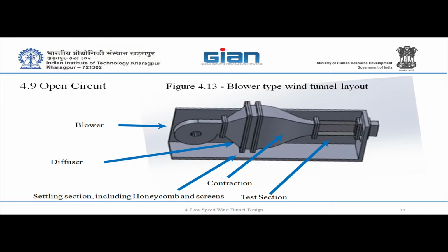Now, of course, you could put your blower outside the laboratory as well. So you will save the noise, but then you will have to take care of the incoming air. It has to be cleaned and filtered, all the stories. You have to take care nobody is sitting there having his break, smoking or whatever.